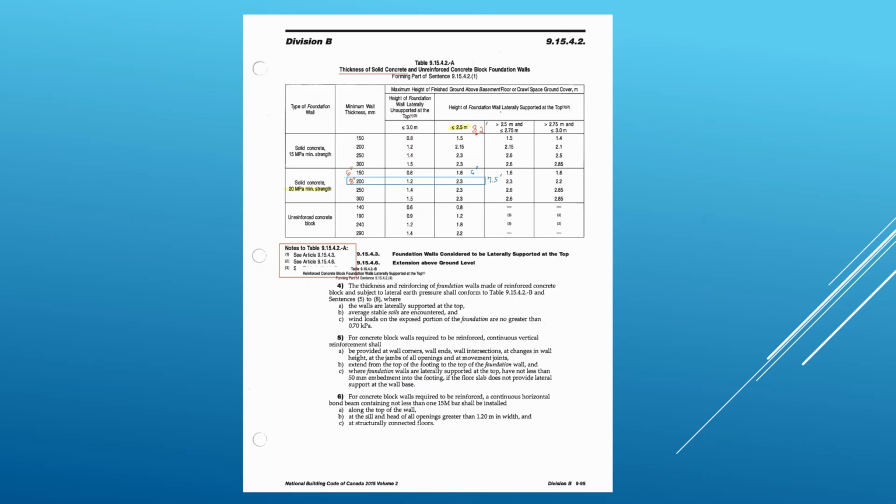As you can see here on the thickness of solid concrete, which would be a normal wall, not an ICF wall, we can go up on less than 8 foot 2 inches. With an 8-inch thick wall, we should be able to go 7.5. So why couldn't we do that on an ICF without the rebar? That's a question I don't know if I've got the answer for, but I'm just throwing it out there for you designers and inspectors.